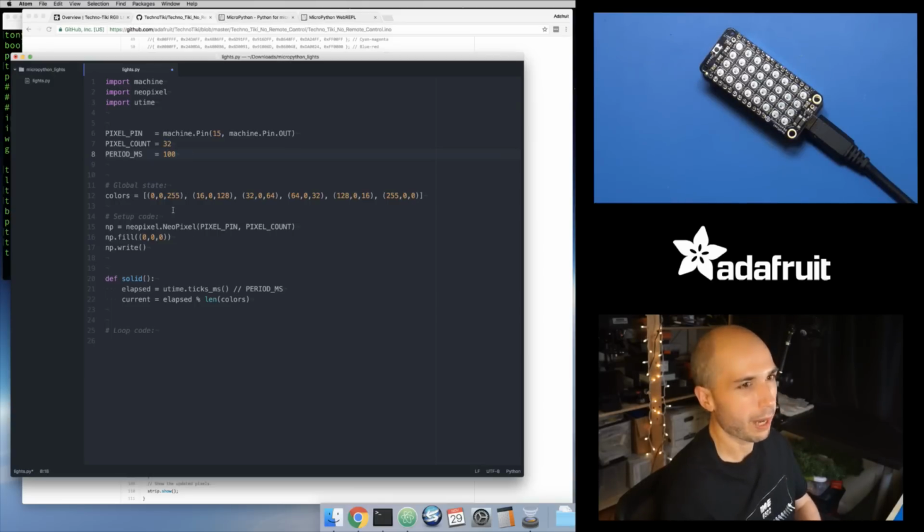After up to that first 100 millisecond period, it's going to be getting this value of 0. After that, let's say my ticks millisecond returns 242 or something as a value. So 242 integer divided by 100 will give me a value of 2. Not 2.42, but 2, because it just gets rid of all that remainder. It ignores it completely.